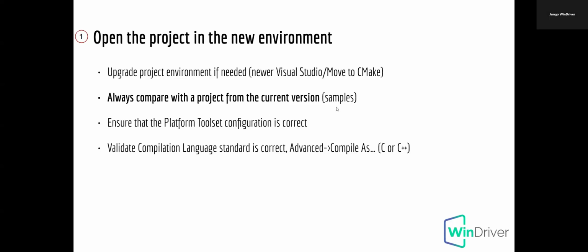on each new version, we have a sample. These samples are working, okay? We develop them to serve as a skeletal code. Not just, but also as a skeletal code. They are great for debugging because, again, they are working. So whenever you are migrating to a new environment with WinDriver, go to the sample folder and see how we formed the code there and what has changed from your version to the latest version, diff it, and it may solve a lot of misunderstandings and time.